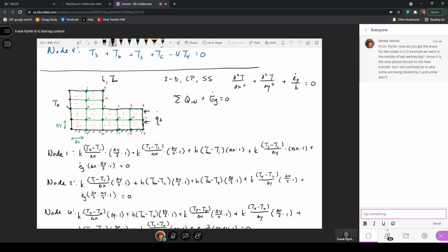And also the last time I explained that if you wanted to solve this problem by an exact analytical method, where you are applying the general heat equation to solve for a continuous expression of the temperature variation, which would be a function of x and y, you would have to actually split this problem into 3 subdomains, so that this top portion would represent a rectangular section, and here there would be another domain to represent a rectangular section